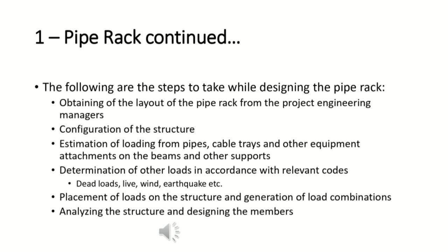1. Obtaining of the layout of the pipe rack from the project engineering managers or the clients. 2. Configuration of the structure. This involves selecting the span-to-span distance of each frame cross-section along the length of the pipe rack system. The maximum distance between each frame should be determined so as not to have pipes which are excessively spanned and then they will begin to sag.